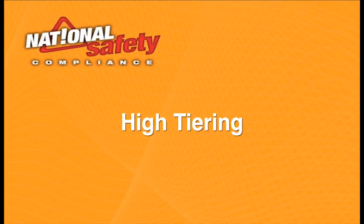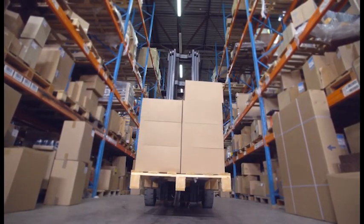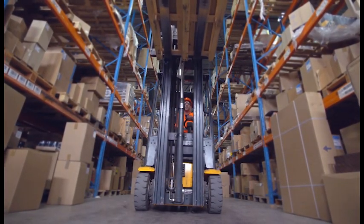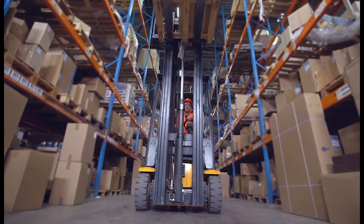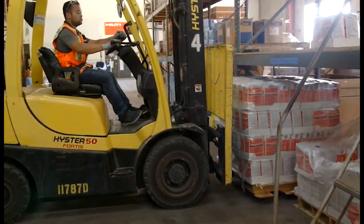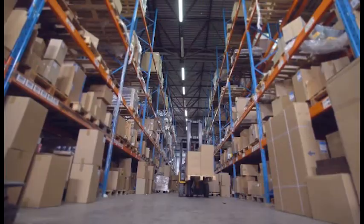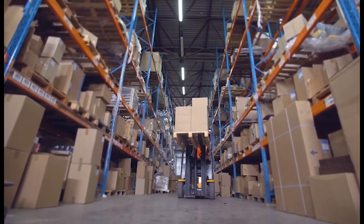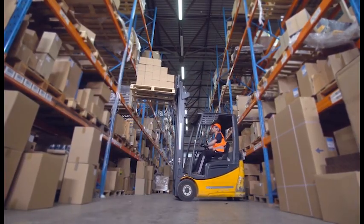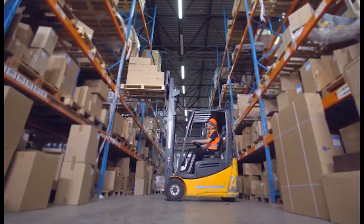High tiering. Reach trucks are often used for high tiering, which involves stacking loads in multiple tiers high off the ground. This is common practice in large warehouses with multiple large shelving units. The heaviest loads should be on the bottom tier and the lightest loads on the top tier. Reduce the load below capacity of the reach truck as the mast is fully extended. Carefully extend the reach mechanism of the truck forward when depositing the load.